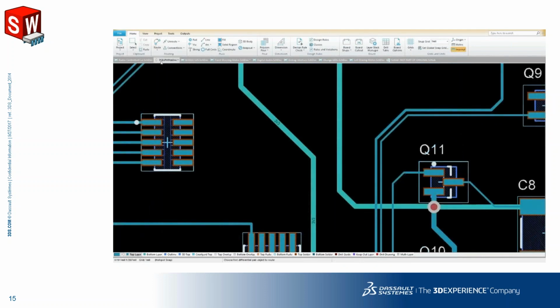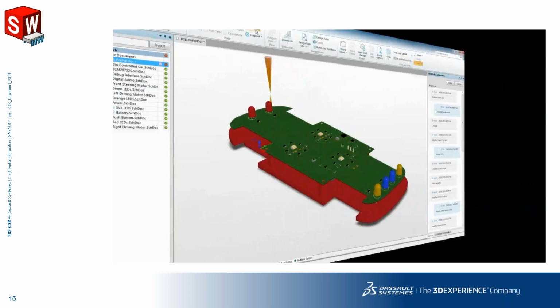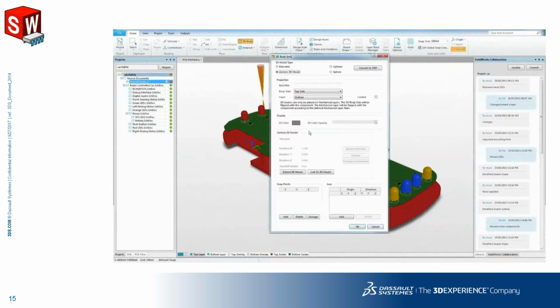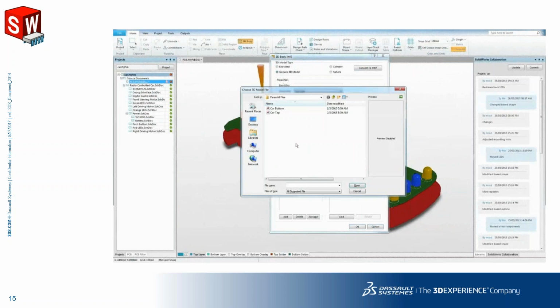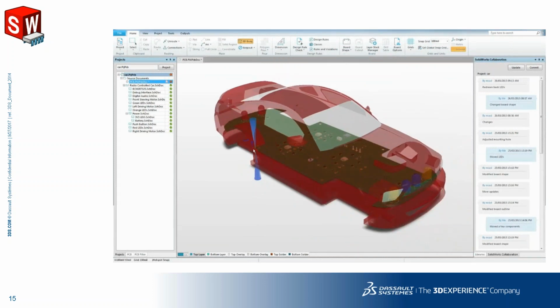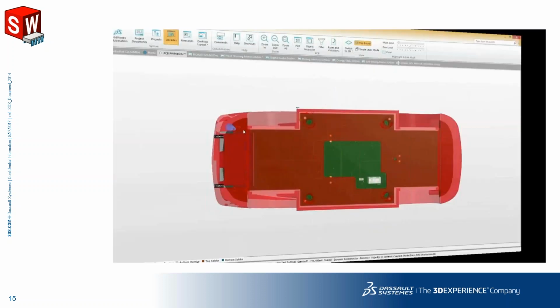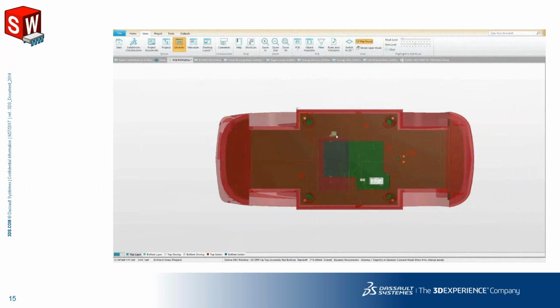One of the most innovative features of SolidWorks PCB is the ability to incorporate SolidWorks models with the PCB design environment. So even if you have a 3D model that you need to import into SolidWorks PCB, you can do that. And you can have a rule check. It's a powerful 3D collision engine with real-time highlight capabilities, which makes it simple and easy to find interference and fit problems. You can see here that any red color is showing that there is a collision.